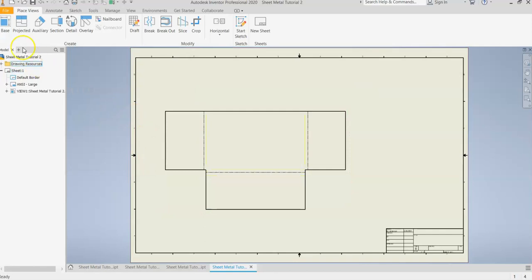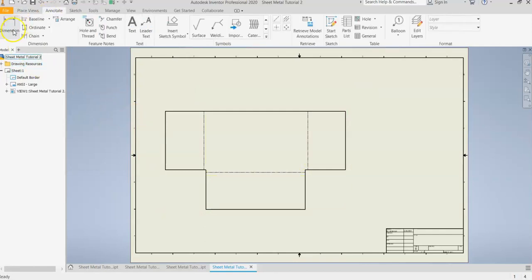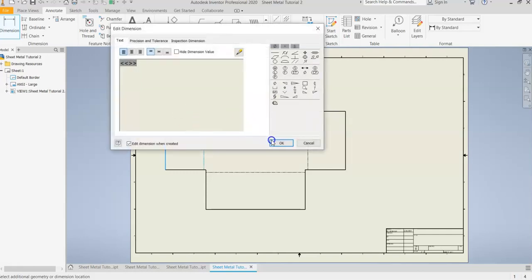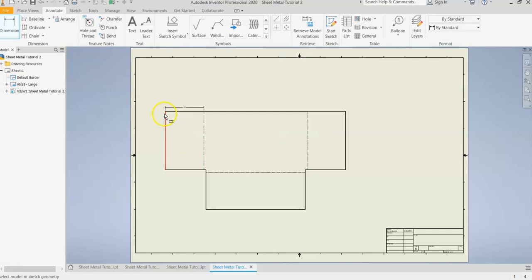Okay, not too shabby. Let's do some basic dimensions right here. So I'm going to go dimension. Let's see. We probably want from here to that first little bend. I'm going to pull it up until it's a dotted line so it locks into that spot. We're going to do the same thing from here all the way out here, next dotted line.